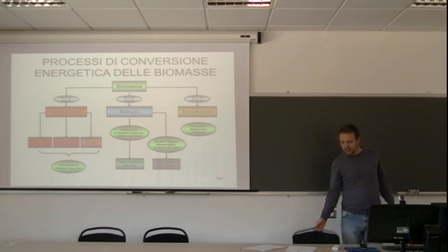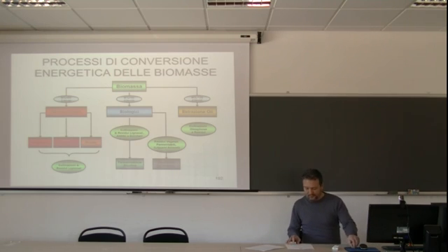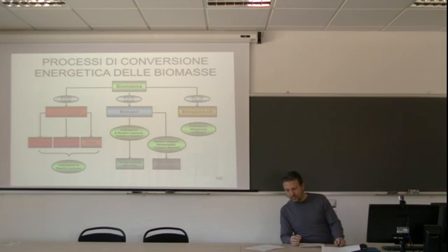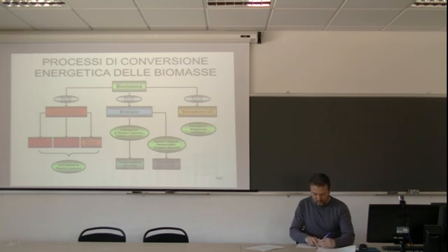nickel coating. Yeah. Because I came across a specific case where the nickel chrome keeps on overlapping each other and induces high corrosion rates over the time of weeks. Ideally you want a protective oxide layer like chromium oxide on top, or any oxide, but it should be protective, conductive and consistent. If it's consistent, then there won't be any gaseous diffusion which will attack the substrate.